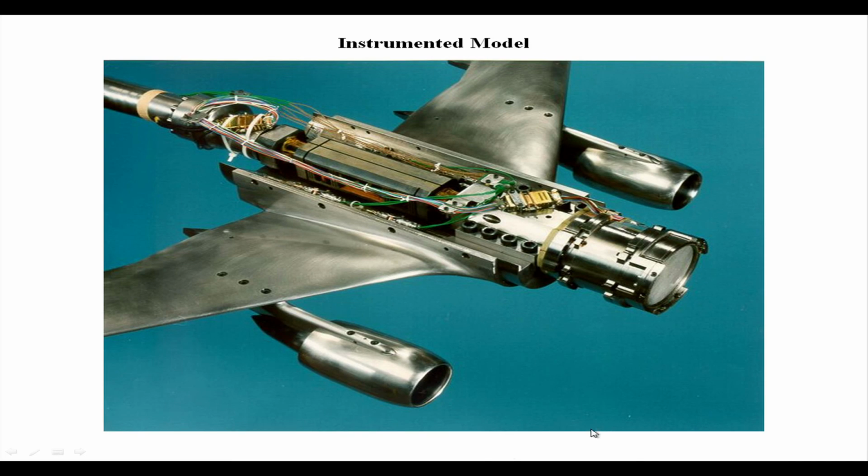So we first choose which model we are going to put in, because we have a certain problem in mind. Based on that, we have fabricated a model in such a manner that we can position and hold it properly in the test section of a wind tunnel, instrument it properly, and then hope to perform some experiments. So what we see over here is a very well instrumented model.